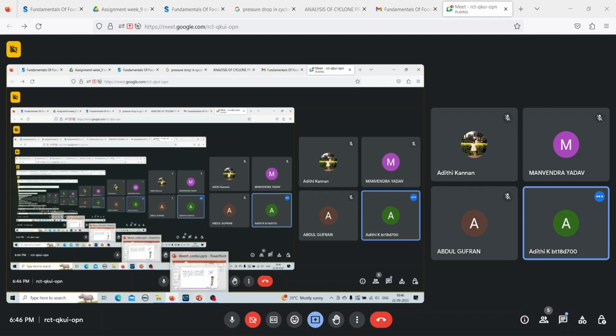So v, I am substituting as 15 meter per second. Here, the diameter is given as 0.3 meters, so I am substituting the radius as 0.15 meters, and the acceleration due to gravity as 9.81 meter per second square. So if I calculate this, I get a separation factor of 153. The answer here is option A.